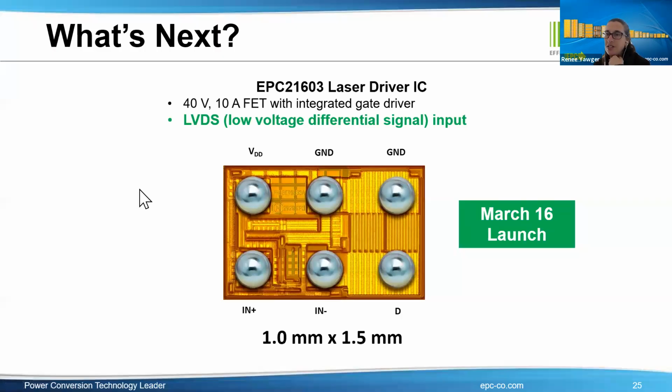Do the devices have tolerance to humidity? All our GaN devices are glass passivated, and so they are as immune to humidity as any plastic package part, even more so. They all pass not just humidity testing for automotive, but are also rated MSL1, which means they're the most immune to the environment in storage. Basically, because GaN is built on top of silicon, we can seal it in a glass case from the rest of the world, and the only penetrations are for the solder bumps.